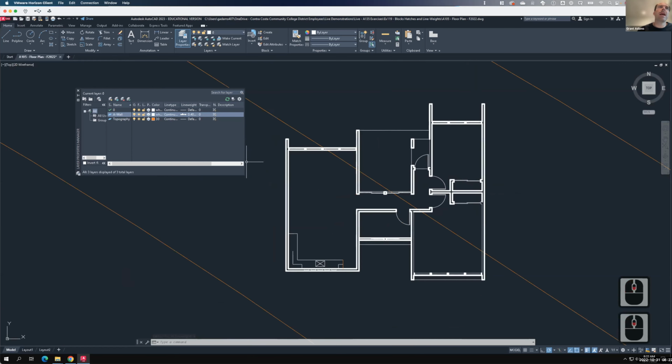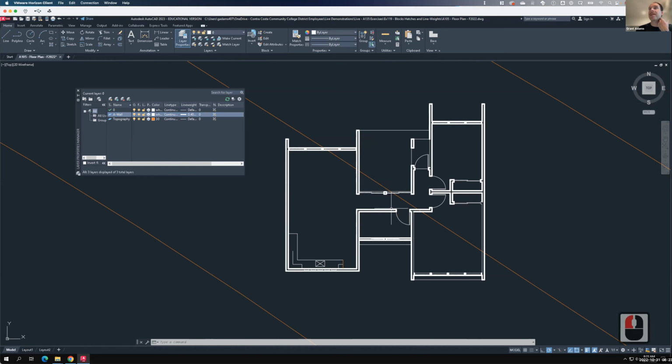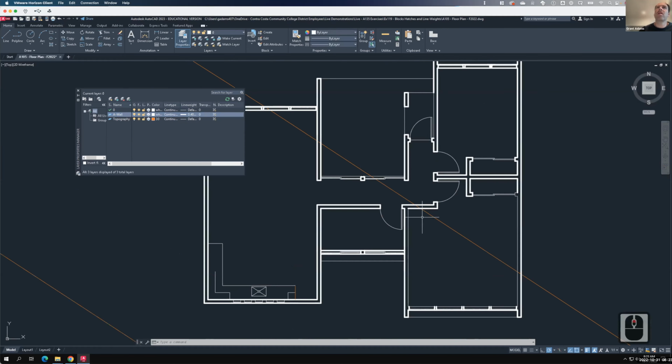You will see any line weight that's above about a 0.25, 0.3. Any of the smaller line weights will just look thin until you go to print. And so that's an unfortunate consequence in AutoCAD. We just can't see the lighter line weights. So I have my walls set at that thicker line weight. That's what I wanted them set at.